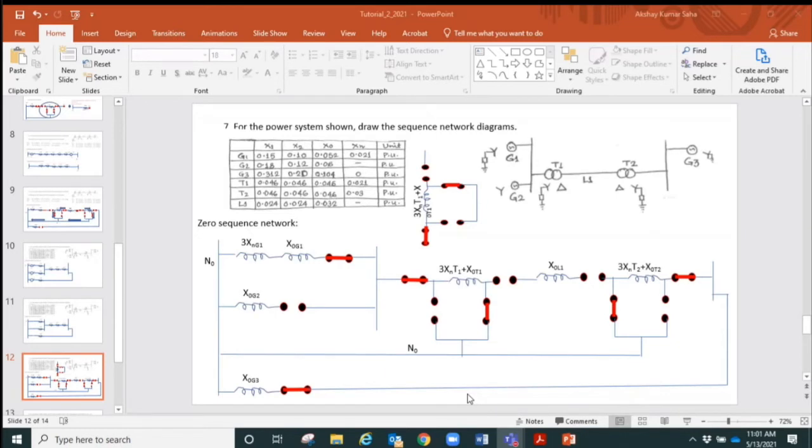It's the Y connection, star connection. Yes, and is the neutral point grounded? No. If the neutral point of any star connection is not grounded, it does not allow any zero sequence current to flow in the phase or lines, which we studied long ago in the theory. So you need to go back there if you forget why.